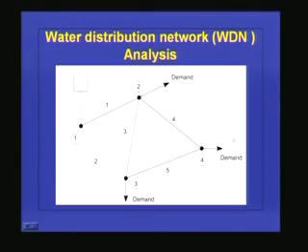So if this node 4 is catering to a certain number of people, depending upon that population and the supply rate, let us say 100 LPCD or 150 liters per capita per day or whatever, I will be able to find out what the demand is. In the network here, I have already given you the configuration. I have given you the layout, and I will give you what the demand is here, here, and here, and this particular network is being served by a distribution reservoir here.